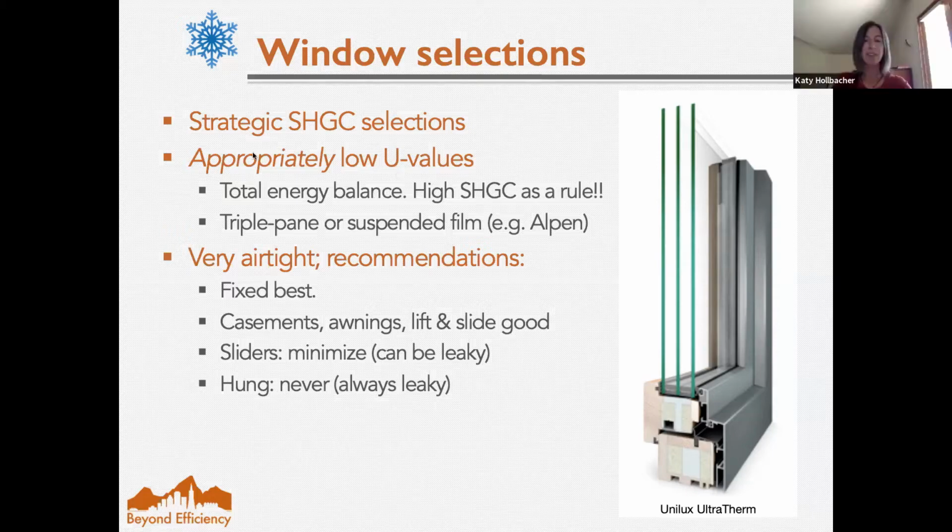You know, in some cases, all the gorgeous views are to the west. There's significant thermal comfort concerns and just cooling load concerns. And that's a situation where it certainly could make sense to do a low solar heat gain specification on that window. But as a rule here, just be careful of asking for the lowest U value product, because on a net annual basis, when we look at total energy balance on the whole building scenario, you could significantly increase your heating load.